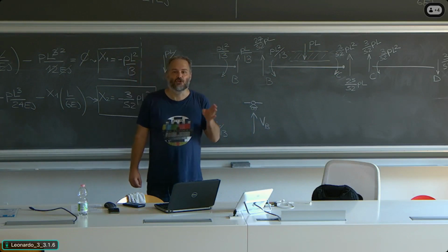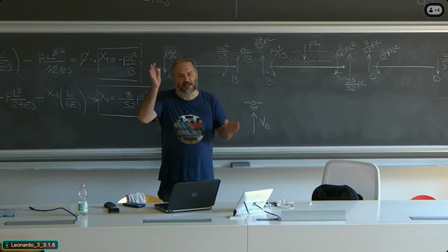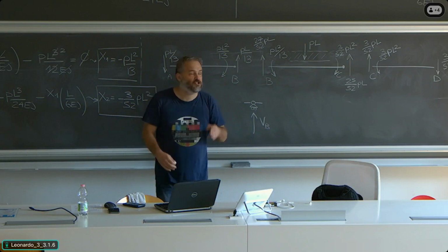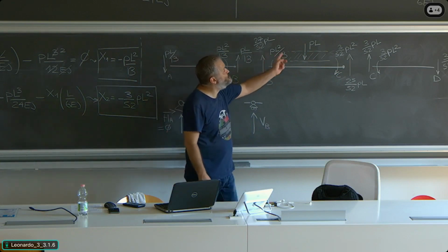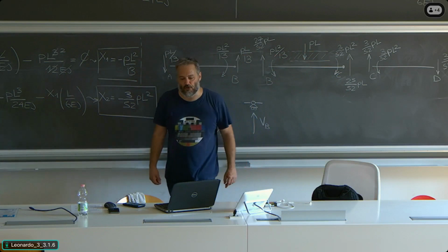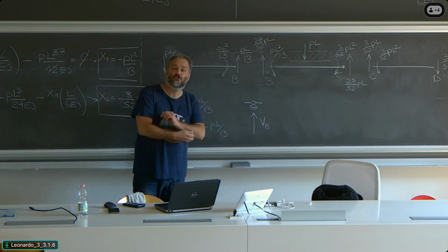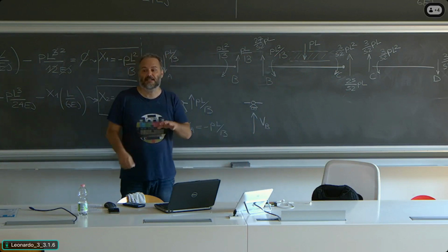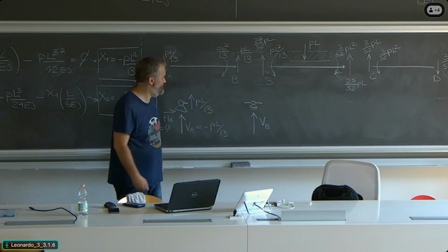No matter what the bending moments are, the ratios between the two forces can change. In this case, we have a ratio between the two forces which is 4/3, but the sum of the two should be equal to the load applied, be it distributed or concentrated.